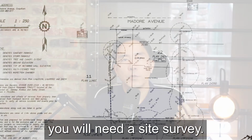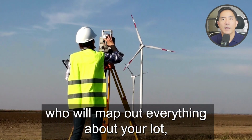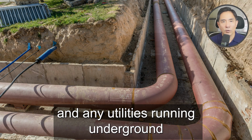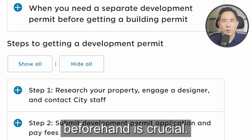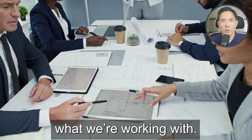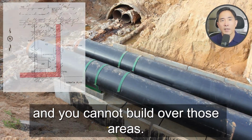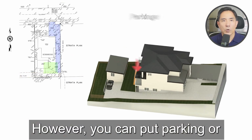Next, you will need a site survey. This is done by a licensed surveyor who will map out everything about your lot, like the exact property lines with the existing structures and any utilities running underground or above. Knowing any development restrictions beforehand is crucial. Once we get the site survey, we can better understand what we are working with. I've dealt with lots where there were right-of-way or underground city-owned utility lines, and you cannot build over those areas. However, you can put parking or driveways there.